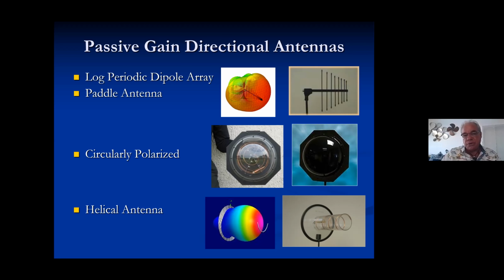Now, you can see that circularly polarized antenna, which happens to be the inside of a Sennheiser, I think it's a CP5000. You can see it's a very long metal coat hanger that's wrapped in a big circle. That's essentially what it is. So if you really get stuck in a jam on a show, you can go to costuming, grab a metal coat hanger and use that. It won't be great, but it'll work. That's all these antennas are. The helical as well is a bunch of screen door parts, but they're just put together in the right way.